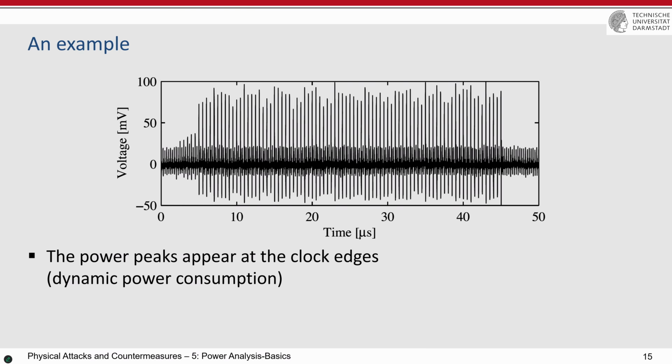Now you can look at the power consumption trace and see, the device was idle, but now it does something. And you see here that it's increasing. And if you look carefully here, there is a high peak, low peak, high peak, low peak, high peak, low peak. There is a low peak in between, and this is exactly this negative edge of the clock. And then afterwards, the device does not work at all. I mean, it stopped completely, but still you see some small things. What are they? Again, data inactivity, but there's a clock tree, there's a flip-flop.